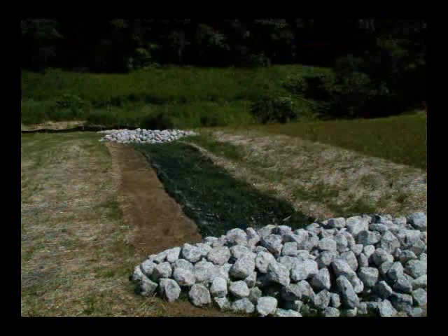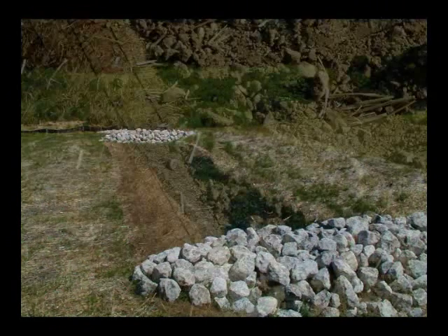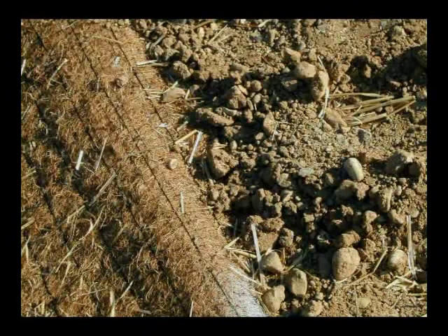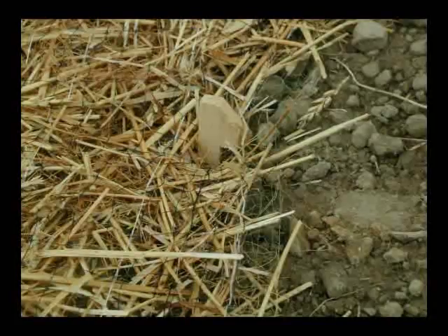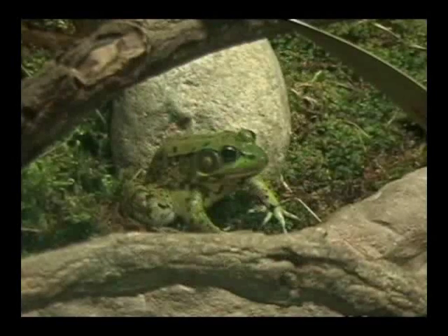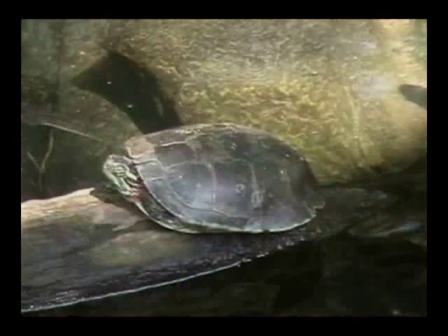The blankets are generally made from straw, coconut fiber, or a combination of both, and are reinforced with netting. Refer to the manufacturer's specification for the proper application of erosion control blankets. Typically, erosion control blankets are installed parallel to flow. They must be trenched in at the top of the slope, overlapped at the sides, and secured with special staples or stakes. Care must be taken to ensure that there is a good contact between the blanket and soil. When selecting erosion control blankets, consider using biodegradable blankets and stakes when the area will be mowed or where wildlife such as snakes and turtles may get tangled in the netting.